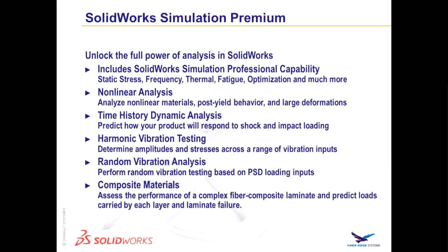One other thing I'll just mention briefly, even though we're not going into detail about it, is that Simulation Premium also enables you to use composite materials in your linear stress analysis. So if you have carbon fiber or other stack-ups that you need to simulate, you'll be able to specify all the plies of the material: how many layers there are, the thicknesses of each layer, and their orientation. That way you'll be able to get a much more accurate picture of the stress inside those composite materials. And you'll even be able to predict things like delamination.